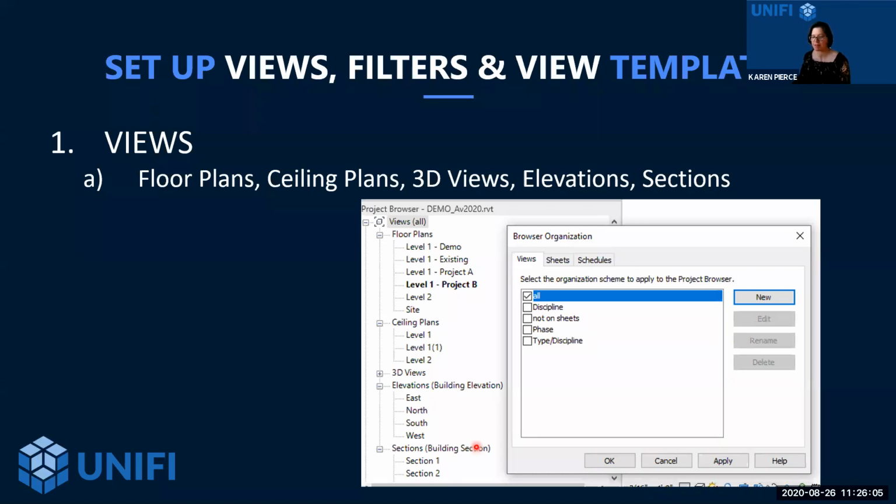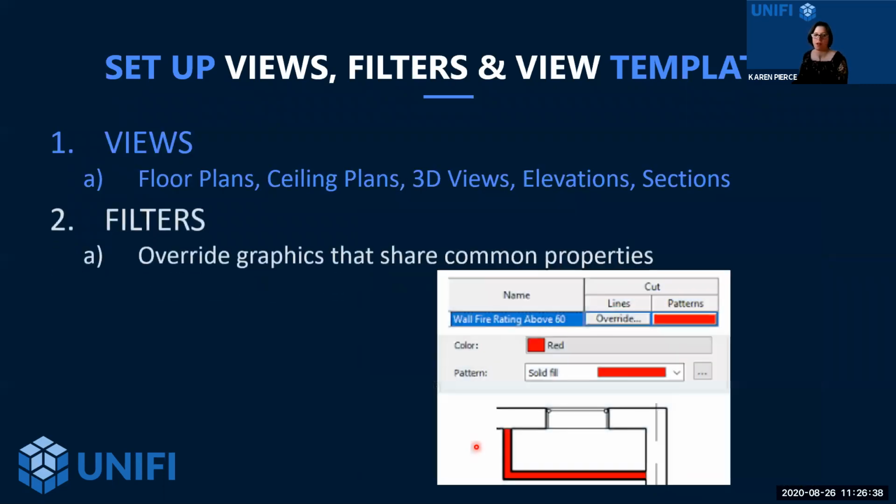And with those view types, like if I'm looking at a floor plan interior versus perhaps a floor plan electrical, granted that might not be all within the same discipline or the same model, but the idea is I could actually create, and we're going to get into in a second, a view template associated with that floor plan. So I can go create new floor plan type A, type B, and actually set my views to already correspond to that. So once I found that out, I thought it was really amazing. Definitely just click on edit type and you'll see what I'm talking about within the Revit environment.